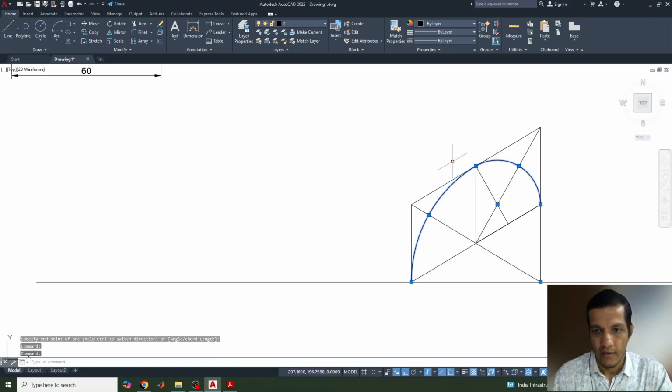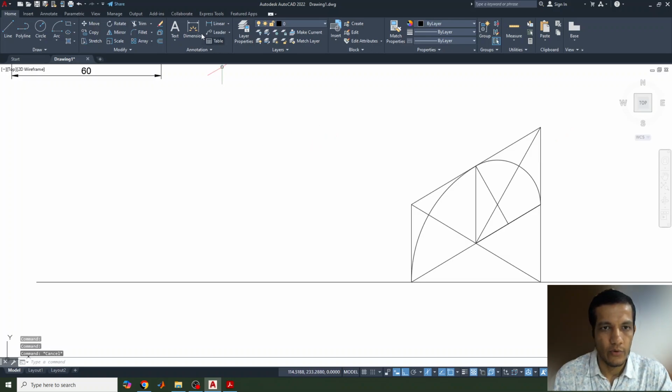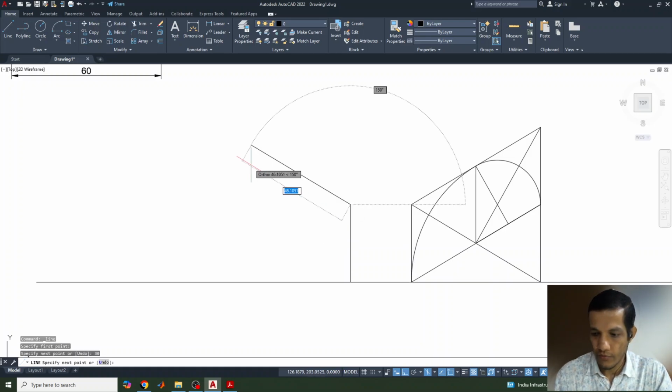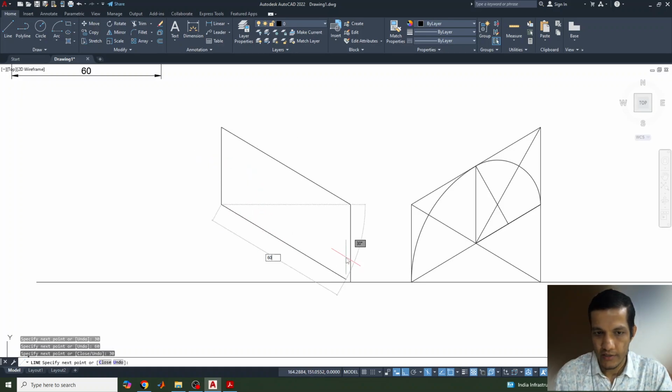semicircle we drew. Next, this is iso right side, another one we will do for iso left. So I'll click on F5, and you can see it has changed to isoplane left. Now select the line here and take the height, 30, again we'll go for 60, again come down 30, again come this side 60. So now this is completed.